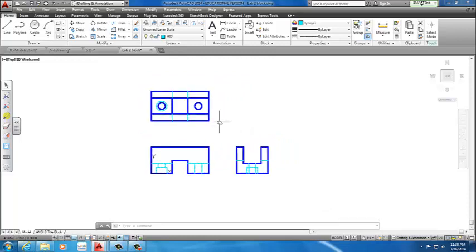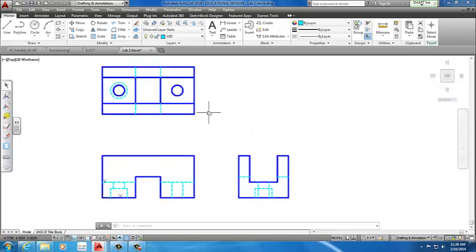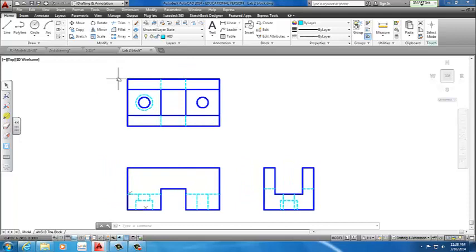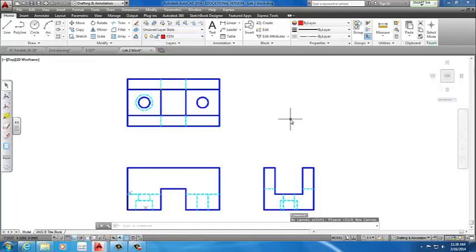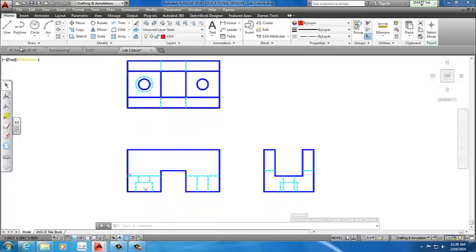If you are missing data, the next part we have to do is annotate, create center lines to show where our circles are located. You just create a box following the box that's provided, and then you type in whatever you like. Use the layer tab here, and we change it to center lines. And that time we're going to play around with the sizing. If it's not in the right position, of course you can move it based on your preference. There is no specified distance.